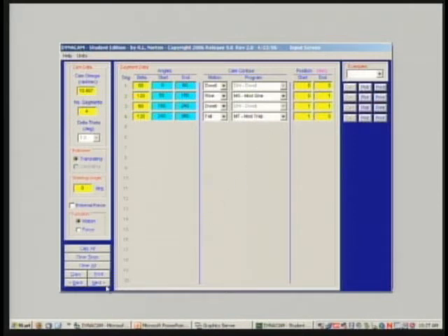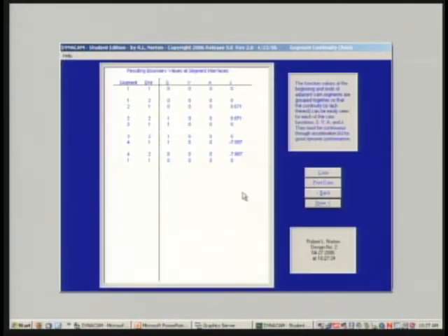And when you're done with that, you can hit the next button, and I bring you to this screen, which says resulting boundary values at the interfaces. Now I've arranged this screen so that I can check students' work very easily to see whether they've obeyed the fundamental law of cam design, and that means you can check it before you hand it in to your instructor. What I've done is I've grouped the values of S, V, A, and J at the end and beginning of each segment together.